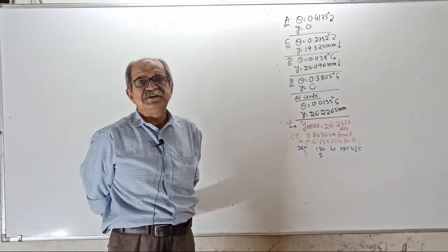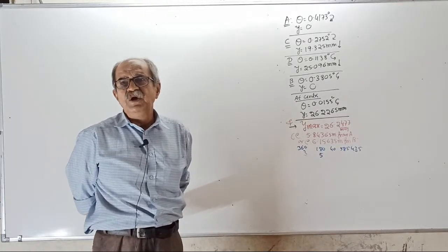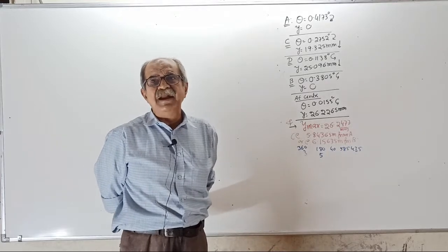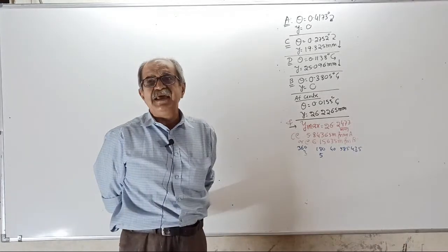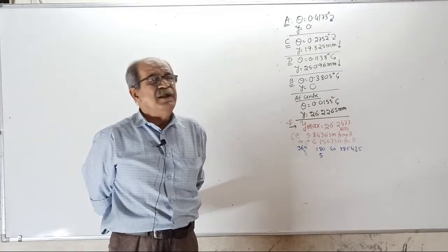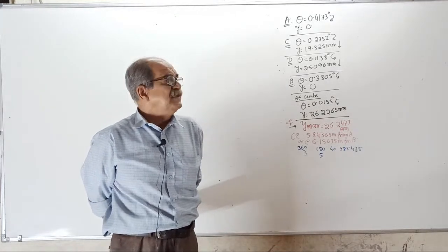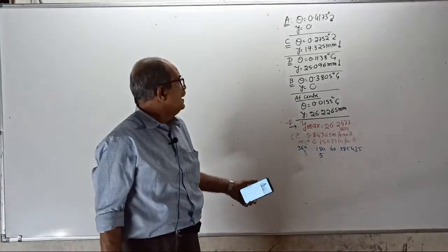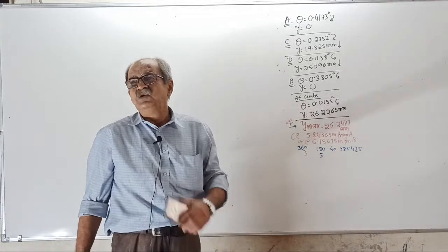That is called the strength aspect. Then we have the serviceability aspect. Usually we check deflection by the L/D ratio, but in some special cases, especially when deflection is very severe, it is advisable to go for actual deflection calculation. So in case you want to find deflection, you can use software.